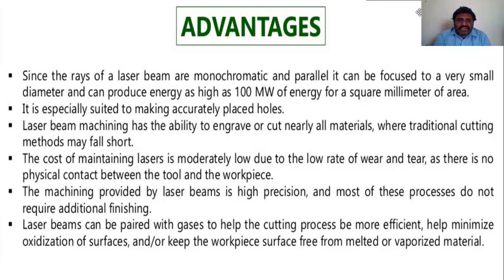Here very traditional cutting methods may fall short, and the cost of laser machining is moderately low due to the low rate of wear. We know that tool wear takes place very little here, and there is no physical contact between the tool and the workpiece, because the laser acts as the tool, and no tool is in direct contact with the workpiece.